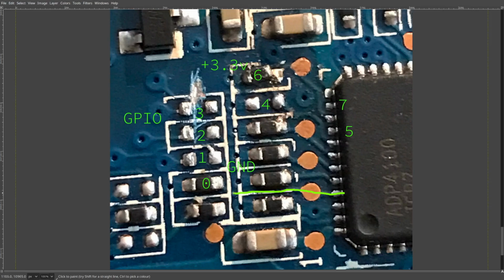VID 0 just comes past here and then to this resistor, through the resistor to the via. So if I want to disconnect VID 0, if I desolder this, we're all good. It's already disconnected. All of these vias here are for ground, so these resistors are all pull downs, 10K pull downs. This really isn't necessary. The detail doesn't matter, just leave them alone.